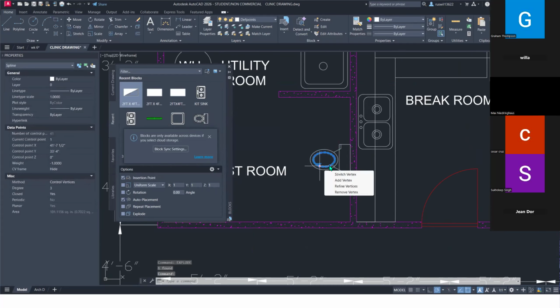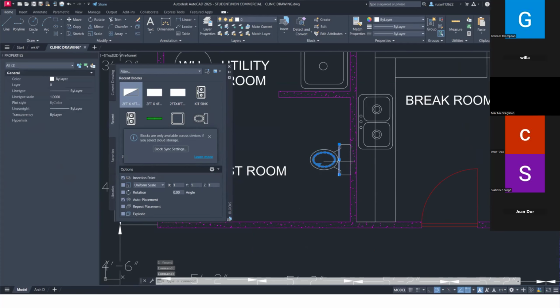When Will originally drew this, it was all line work. He drew the toilet seat, he drew the back of the toilet, and you can see each part of those lines. Once you draw all of these lines to make something intricate, you don't want to copy and paste them around, because at some point you're going to accidentally stretch something, or something is going to move on you.